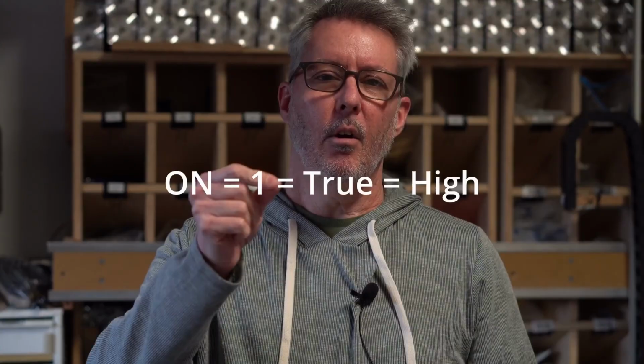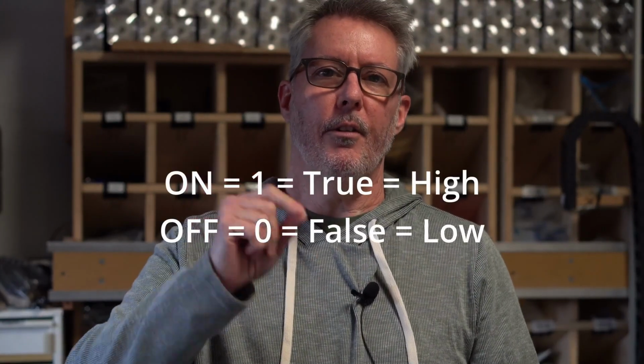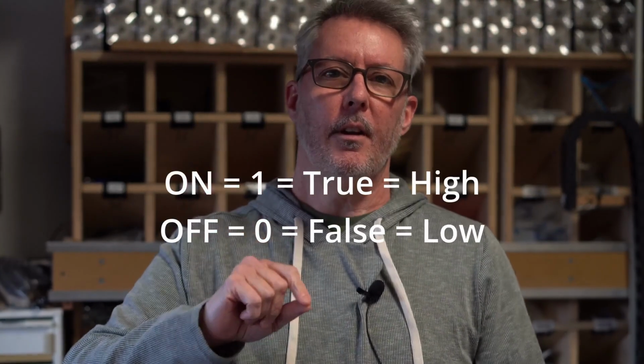I'm going to show you the lines of code that you'll be using the most. The way to control features and enable features and set features of the microcontroller is to control bits, or turn on and off bits in registers. Bits are ones and zeros, and the microcontroller is made up of a bunch of registers, which is like a huge set of control panels with a bunch of switches. Each switch is like a bit. It's either on or off, a 1 or a 0. On is 1, off is 0.